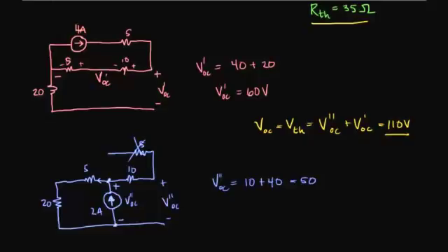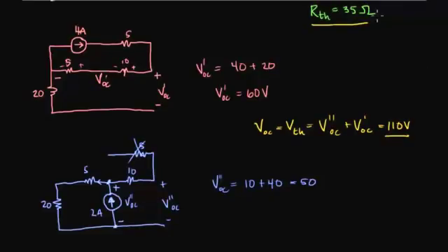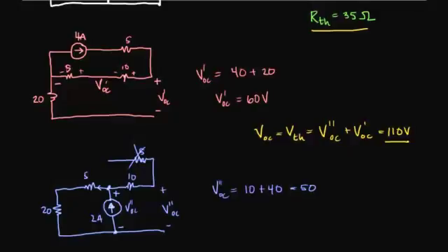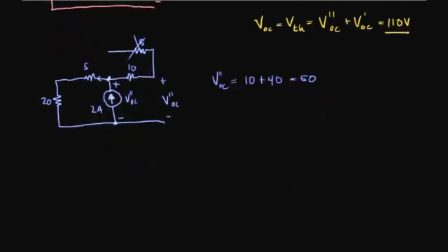So let's draw our Thevenin circuit. Okay, and with both of these, my other example didn't show this, but if you get these negative, well, you're not going to get negative resistance, hopefully, if you do the math right. But if you get a negative voltage, you just want to flip the polarity from your standard Thevenin voltage. But we didn't get that in this case. So let's draw this.